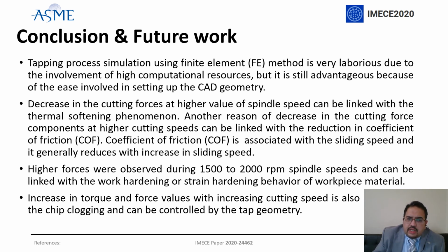The increase in the torque and force values with increasing cutting speed is also a representation of the chip clogging action, and it can be controlled by the chip geometry.